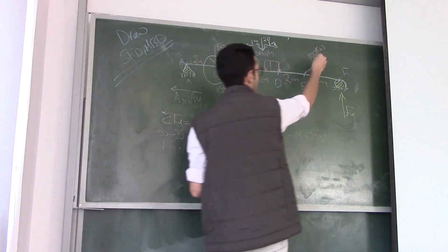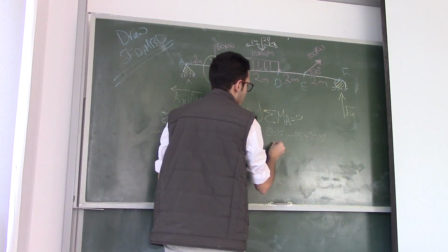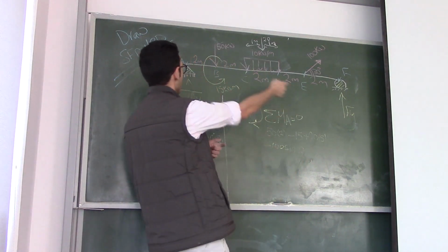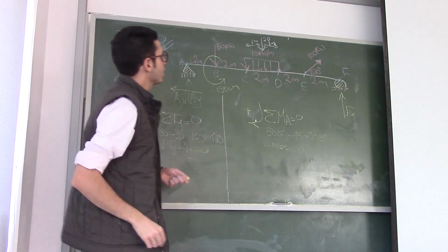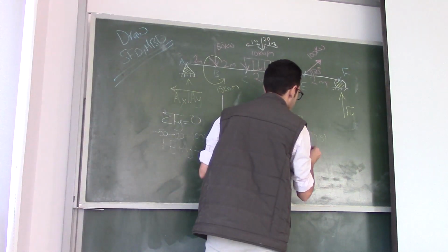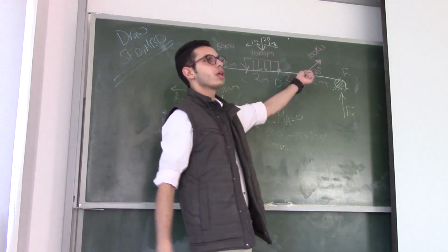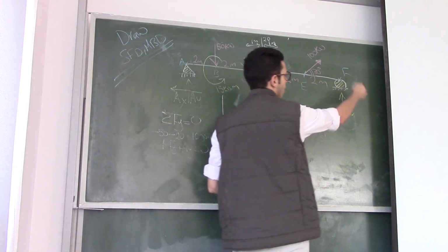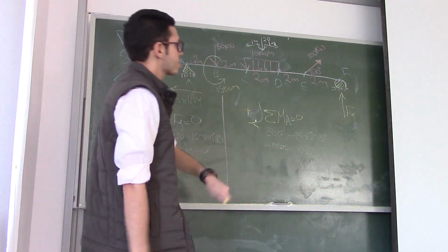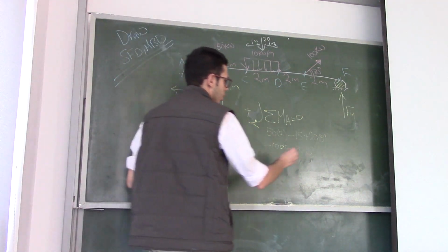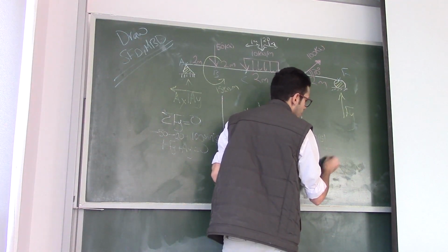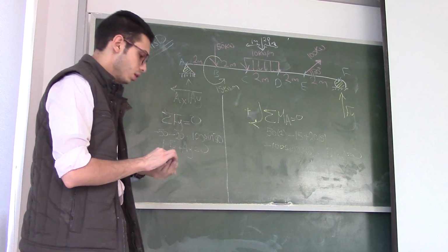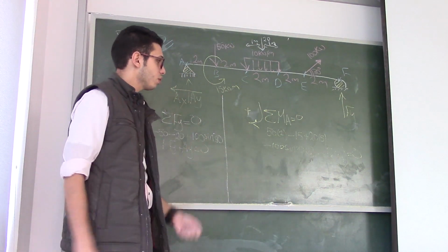And we have this force upward. It makes a minus 100 sine 30, minus because it makes a moment at point A counterclockwise, and the distance is 8. The X component of the inclined force does not make any moment, 0. And finally, Fy makes a counterclockwise moment, and the distance is 10. So minus Fy multiplied by 10. All of these should equal 0. So can anyone tell me what is the value of Fy?